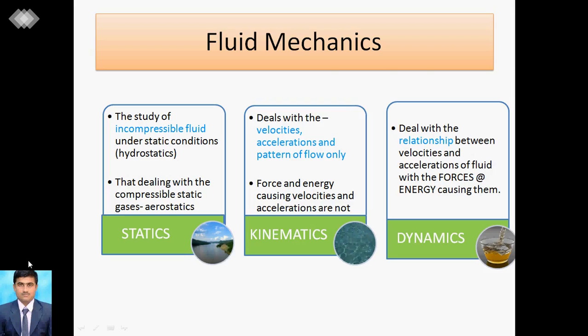Now we move to kinematics. While discussing kinematics, the fluid is in motion, but pressure forces are not considered here. So it deals with only velocities and accelerations, or you can say it is the study of motion geometry. An example is when a car is there, the fluid, or air, moves over the body, so that path can be analyzed by kinematics.